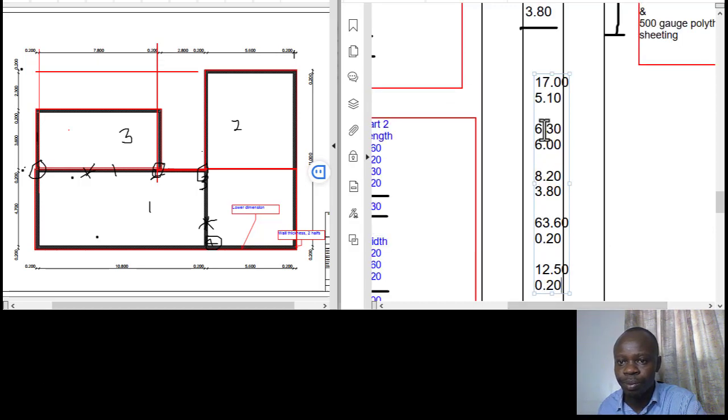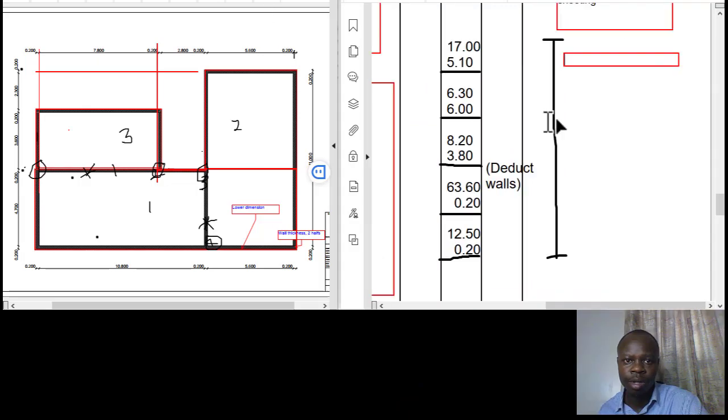Once you have all the items taken note of in terms of the total area for the slab, you just indicate the area of the walls that you need to subtract by indicating that you need to deduct the areas below it. At the time of squaring, they might have a negative sign or any other item, as long as you can make a reference so that you know that you are adjusting the total area for the slab to have the area for the hardcore. Since the hardcore is placed within the walls, you need to have it net.